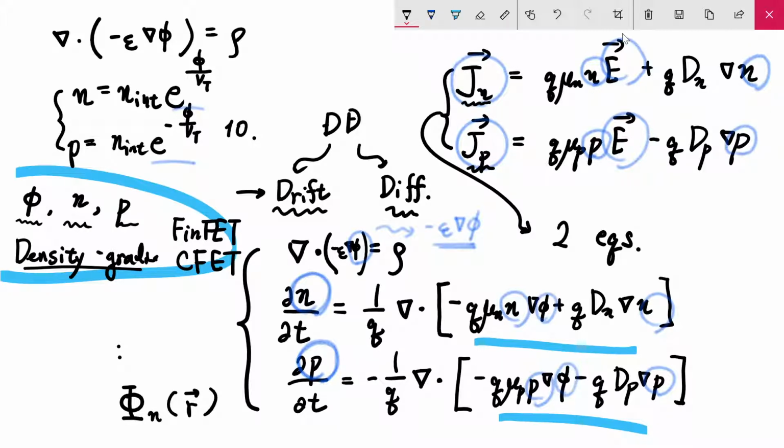And of course, you may say that, okay, then why don't we have 5? Why do we have 4? Usually in order to reduce the computational burden, if you are talking about the NMOSFET, then usually you consider quantum potential for electrons, and if you are simulating the p-type MOSFET, then usually you consider just the quantum confinement for your holes. It is because they are inversion carriers, and only inversion carriers experience strong quantum confinement effect. So in the case of NMOSFET, usually holes are just left as a bulk state, so we don't have to think about quantities like a hole quantum potential. So this is one thing we can expect from our experience for FinFET.